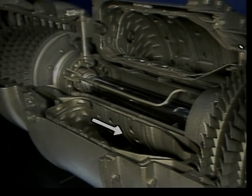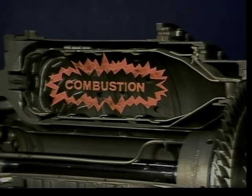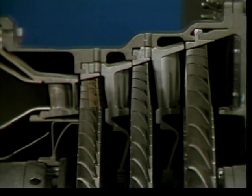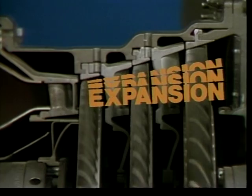fuel is added to the air. This highly pressurized air and fuel mixture is then ignited by a fuel-fed torch. The combustion process releases the energy of the fuel in a temperature rise in the combustor, and after ignition has taken place, the hot gas expands very rapidly and velocity increases. The average temperature in the combustion chamber is about 1600 degrees Fahrenheit. These hot gases expand through the turbine section, deflect the turbine rotor blades, and rotate the turbine rotor.